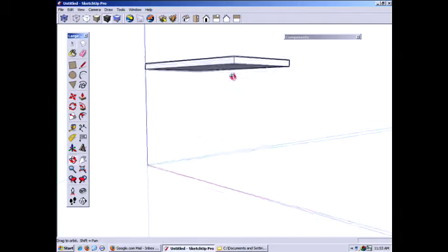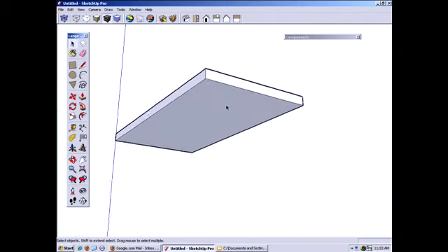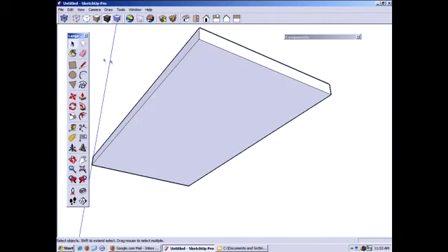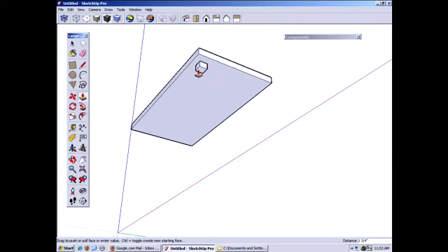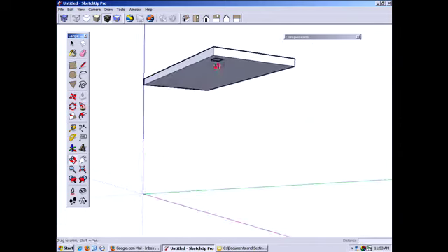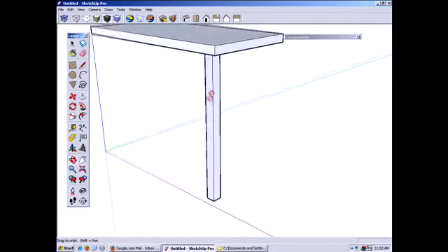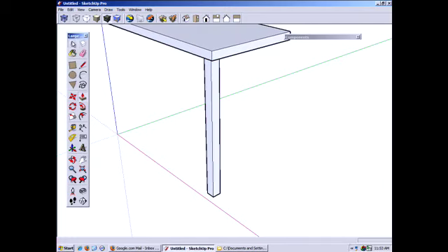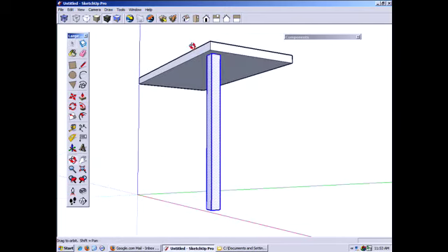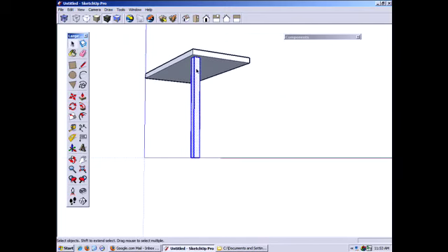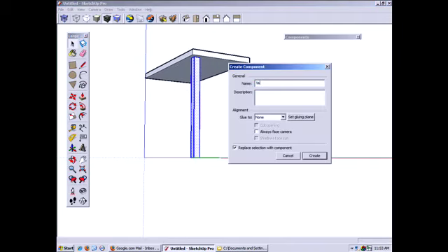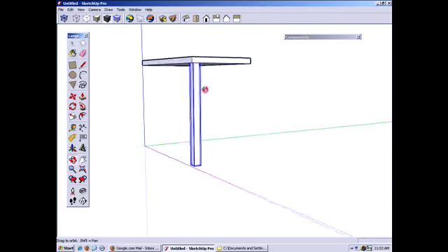Okay. So now let's build out the legs for this table. A rectangle, pull it down. I can access my origin to see how far I want to pull it down. Probably I'll need to make this a little bigger, but I'm going to select that leg, triple clicking on it, and make it a component. Table leg, and create this.